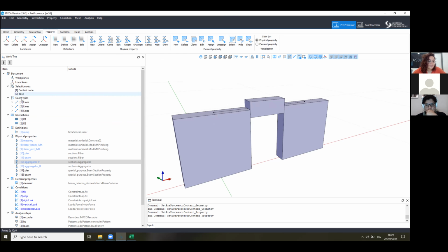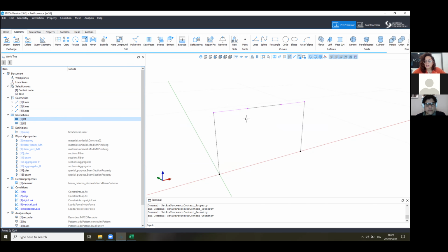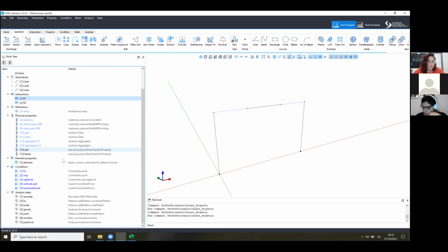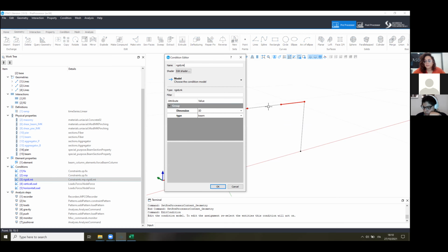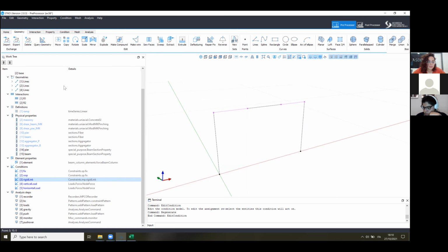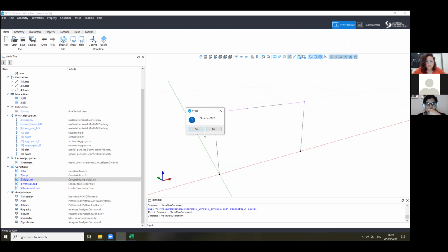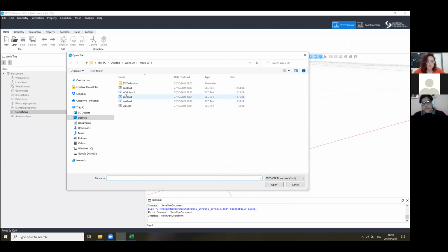To do that in STKO, you can create, I would say two, because you can create one, but to be honest, it's better to create two, because I don't know how this would be organized in a larger structure. So you create an interaction for each of the rigid connections that you want to create, defining a master, a constrained node and a retained node. And to this, you apply a rigid link. So this is one way to do this. I'm going to show you the other one to be fast, that is our second example.